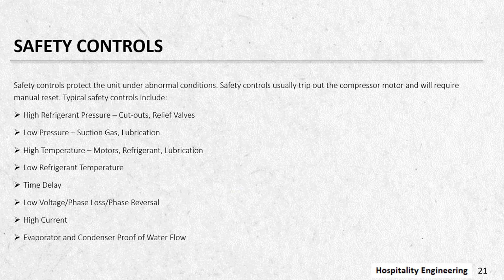Safety controls. Safety controls protect the unit under abnormal conditions. Safety controls usually trip out the compressor motor and will require manual reset.